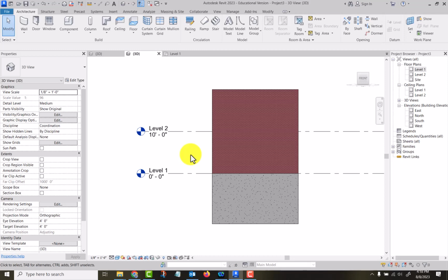So you don't have a concrete wall going all the way up to first floor level all the way around, because concrete's very expensive. So you step the concrete to match the profile of the ground. Well, you adjust your first floor wall to match that concrete foundation wall. So there's a couple of different ways to do things here.